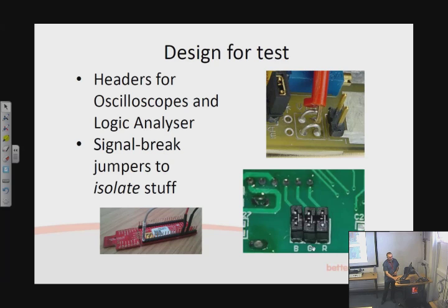And if at the end of the day you don't need those links anymore, fine, you can take the headers out and just put a soldered link in there instead. But that will give you the flexibility you need to configure things quickly and easily without damaging your circuit or interfering with the signal during your development and test.